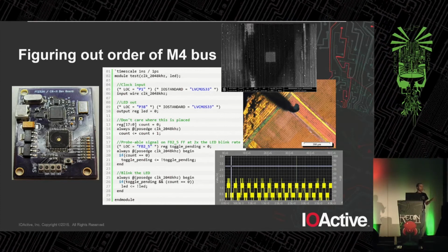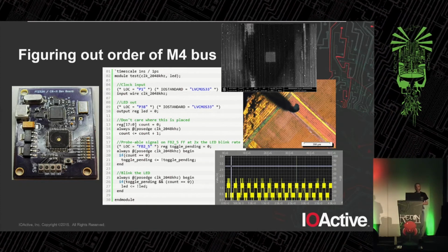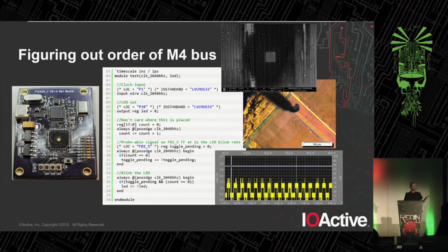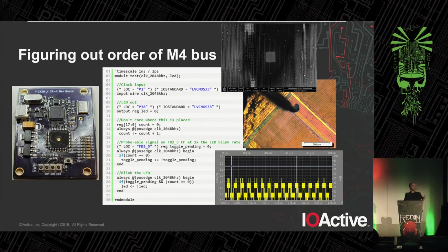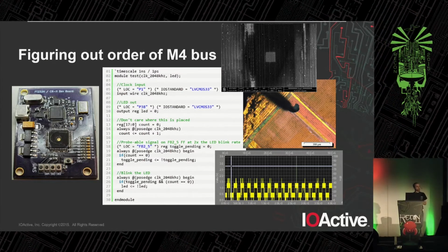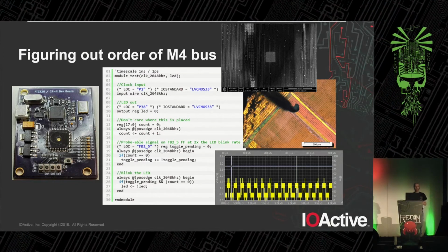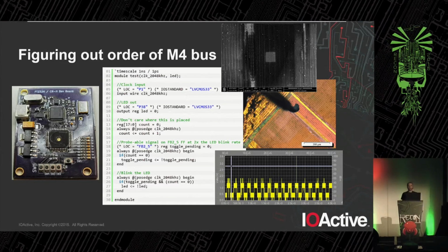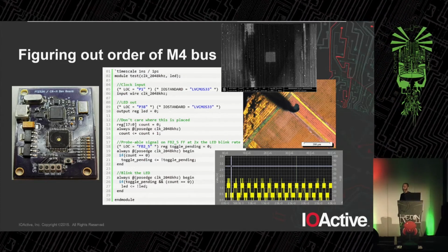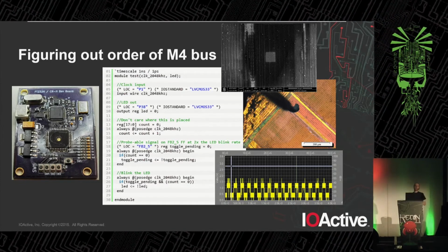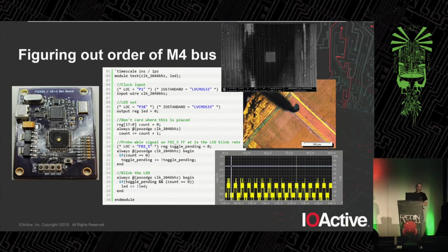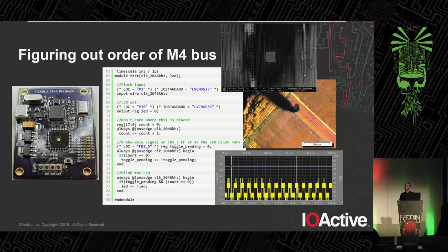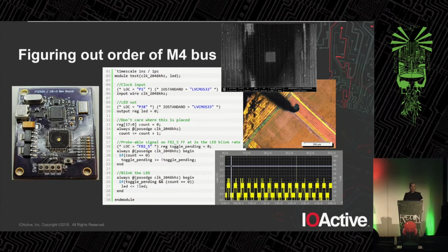Okay, the inputs to function block 2 are probably contiguous. So there's not really that many orderings for the global input pin and these 4 sets of inputs. So let's just try tinkering and see which one works. So I went up to campus, hopped on the focused ion beam, drilled a few holes in the insulator over some wires, and laid down some nice, gigantic 20-micron square probe pads. And then I just started driving signals onto each net.